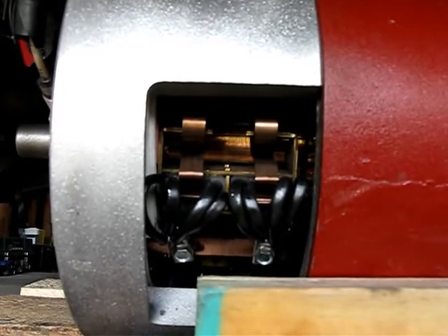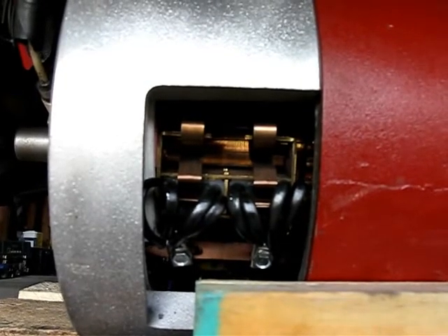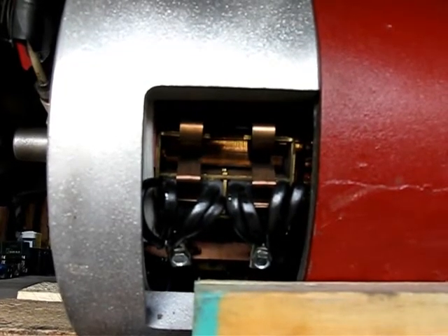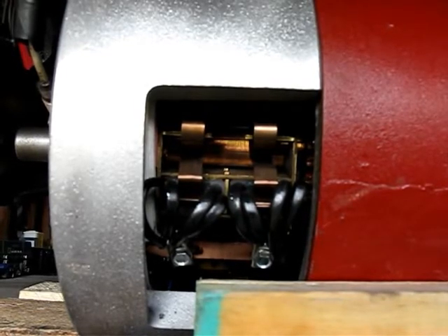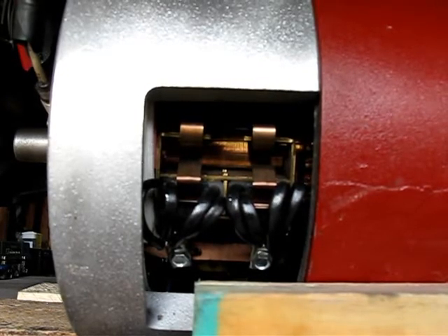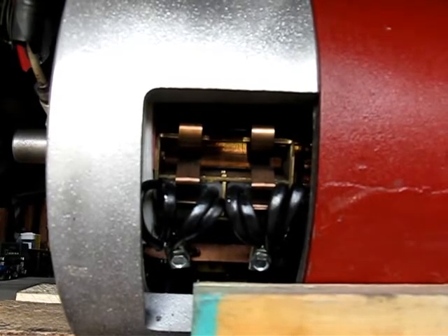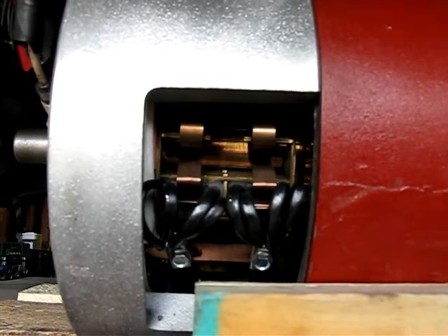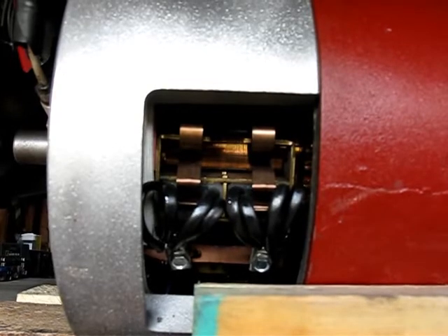Now, I'm not sure if that's applicable to the National brushes that I'm using here, or if it's specific to a certain hardness of the Hellwig brushes, because they do sell them in various different hardnesses for different applications. And I can see that the harder brushes that are designed to I guess last longer would potentially have, just because the material is harder, that it could maybe score the copper of the commutator.